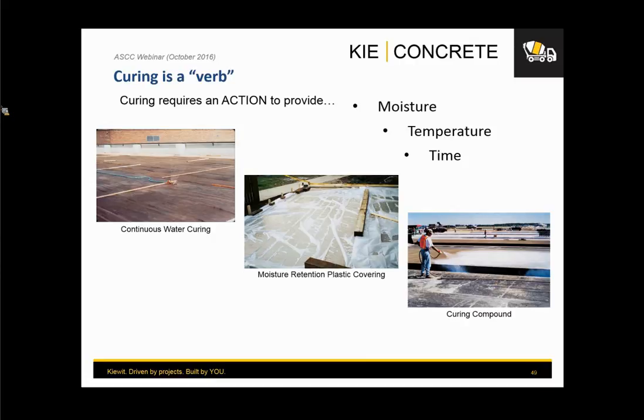And here I'm showing you three examples: water curing, moisture retention, and curing compounds, right? All of them are allowed by best practices in ACI standards, in the field, and in what you typically see in specs. But know that curing is a verb. It requires that we do something. We as concrete contractors need to provide that, right? And if we neglect curing, we are not going to achieve the properties of the concrete that we're expecting. We're not going to get durable concrete. You're not going to get strong concrete. You may actually allow cracking to occur. So we need to be aware of those things, because when things happen, they are going to come back to us as contractors, right?